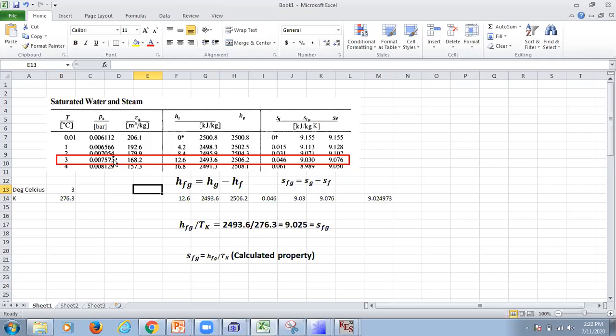See, very low pressure. This is because this is saturated water. So this is the temperature, 3 degrees. So pressure has to be very low for water to be evaporated and have a water and water vapor mixture. So this is the corresponding pressure. Okay. So you have to study this. You have to study the thermodynamics property tables. You study for steam.